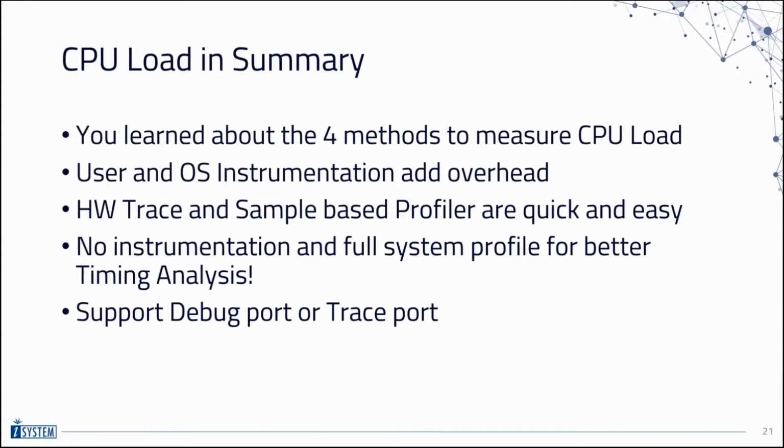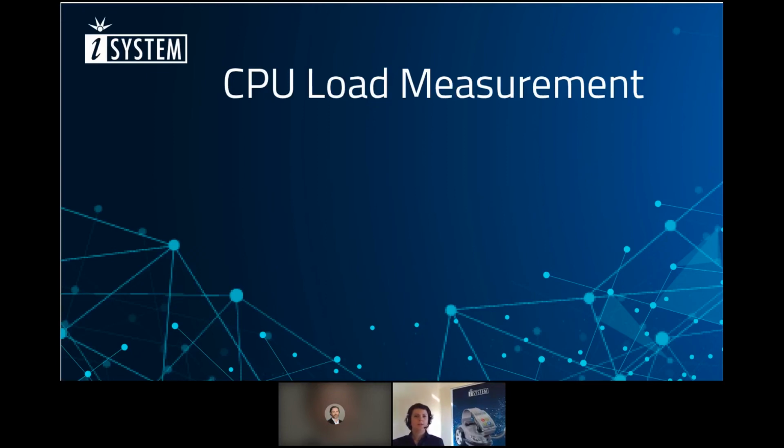Both of those add some overhead to the system, whereas using a hardware trace with the new CPU load inspector and the new sample-based profiler don't require any instrumentation and can get accurate results very quickly. And you get a profile of the whole system for better timing analysis when you need to investigate a local overload.